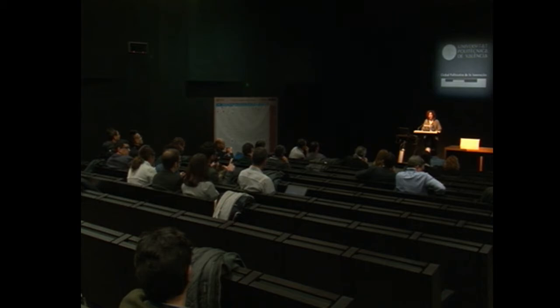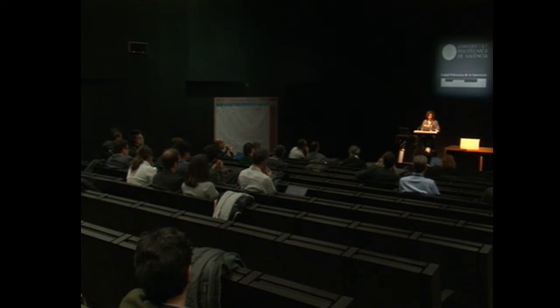Are you working on 6-inch or 8-inch? No, 4-inch. 4-inch? Yes, we work with 4-inch wafer. Okay, we measure the stress, and I think we can deposit this layer without very much stress, but the problem is that when we use the stepper photolithography, to load the wafer it has to be very flat. So maybe making photolithography with other techniques, the stress is not a problem. You have bends, right? Yes.